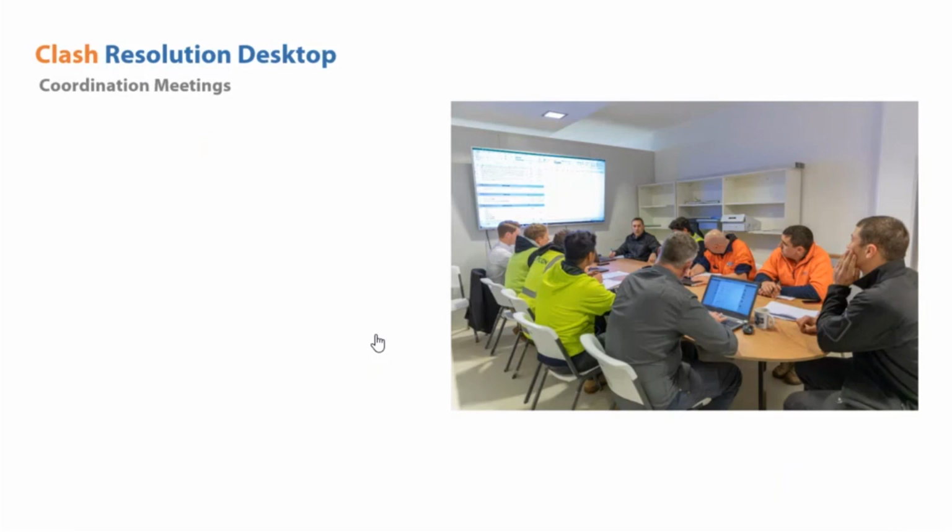The coordination meeting is one important step in the entire process, and there are key aspects to be considered. The first one is the cycle of the coordination meeting. The cycle may vary from one project to another, based on the volume of things to be added in the project, but usually a 1 or 2 week cycle works well. The BIM coordinator, assisted by a technician, may lead the coordination meeting: schedule meetings, send invites to the appropriate stakeholders, and ensure the availability of the meeting room and its technical equipment to be able to project the 3D federated model on screen for review of the clash issues.